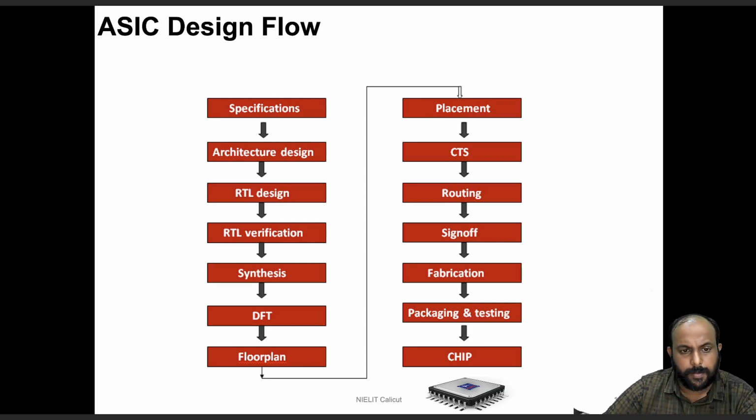They are responsible for building an appropriate architecture of the design. We might be familiar with the architecture of many processors, DSPs, and so on. Basically, an architecture is a representative view of how the design should look, whether it be an ASIC or a system on chip. This architecture will be broken down into different logical portions. For example, the architecture of a microcontroller may carry memories, arithmetic and logic units, registers, control units, and data path units like adders, multipliers, and so on.